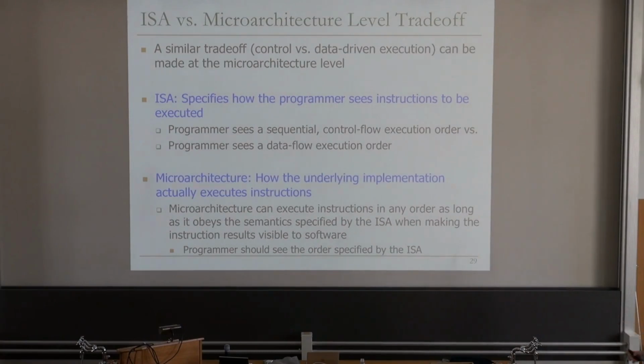And it's growing. Of course, this costs a lot of complexity because now you need to convert the sequential instruction representation into a data flow graph representation internally and store it and then make sure all of that machinery is satisfied. But now you get some of the benefits of data flow. It's not complete data flow. That's why it's called restricted data flow, because you see only that part of the data flow graph that you keep inside the machine. And if you can keep 256 instructions, you can only construct a data flow graph from those 256 instructions. So you see only the partial data flow graph of the program, not the entire data flow graph. But it's beautiful, I think.